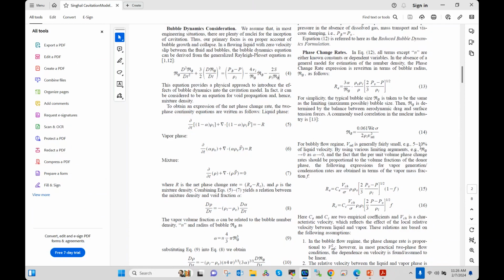So the next question is from Gabor. Which cavitation model is the most accurate for centrifugal pumps? I think we found that the constant gas mass fraction model will do a good job for most of the applications. But in some cases, for example the bearings where you need the inlet and outlet air to be specified, you have to use the variable gas mass fraction model.